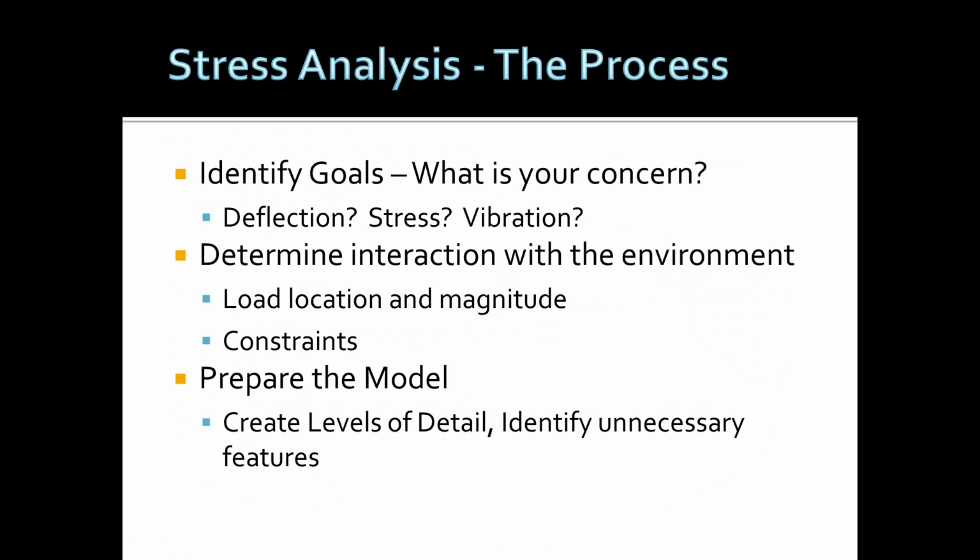You want to look at some of your goals. What's your main focus to get out of this analysis? Are you looking at the amount of deflection? Are you looking at the amount of stress or possibly vibration? Because again, we can do modal analysis with Inventor's FEA. You want to determine how your geometry interacts with the environment, and that goes into how is this bracket fixed? How is it attached? And when it's attached, where are the areas that it can move, that it can flex and bend? And that gets into your loading location, how much load you're putting on it for your magnitude, and then how you have it constrained.